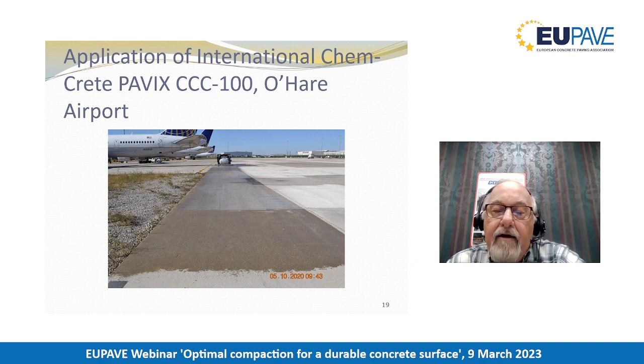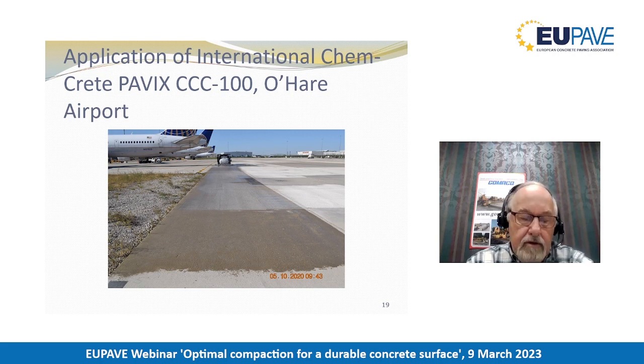But we didn't have any avenue to fix the porosity problem, which was widespread because of the mix design and the construction operations, specifically vibration.